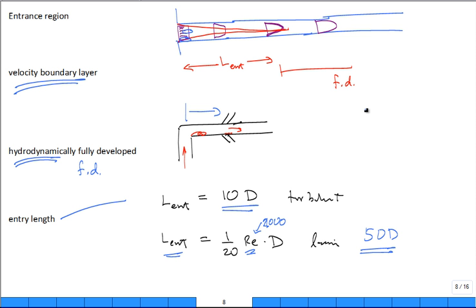That tech said, put that meter in. He went up there and he put it in. He didn't read anything about the meter and how many diameters since a recent bend or anything. And so there's a lot of equipment, I hate to say it, out there that probably are not in the manufacturer's recommended straight section of the pipes. It's just, they got to fit it in, package it in.